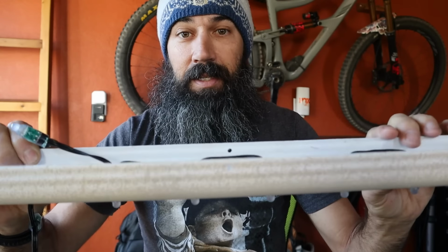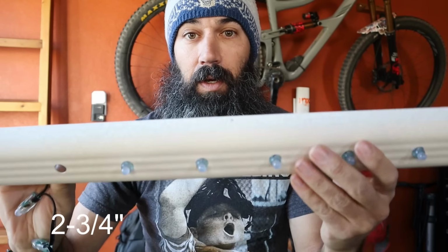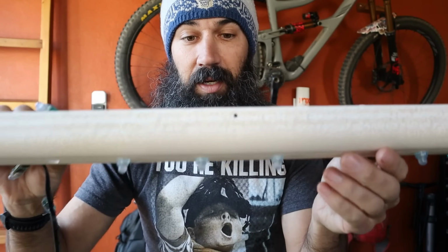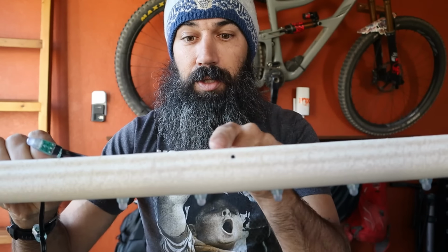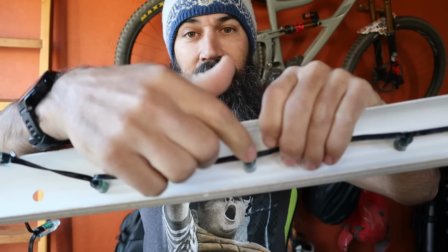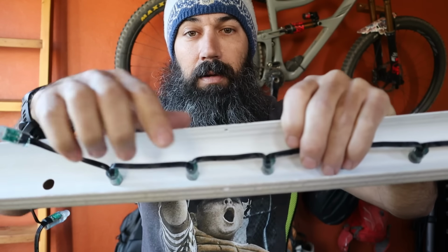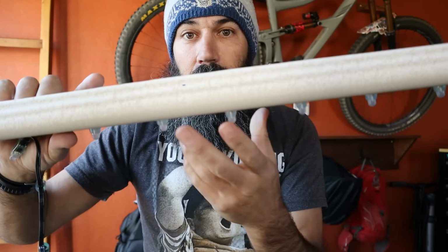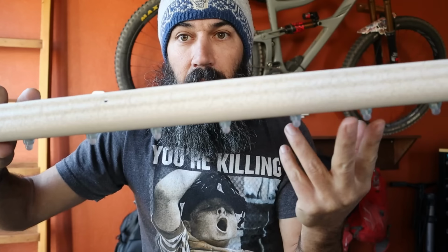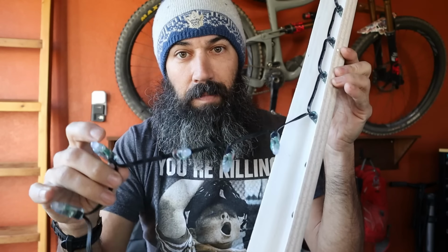Now the next thing you have to know is how far apart to space these for your string or strand of lights. I went with 2 3/4 inches on center. You could go a touch smaller than that, but I would not go any bigger than that. I would not do 3 inches. If you do, you're going to be really stretching these wires apart, and I think you're going to risk severing one of the electrical connections at where these pixels are. So if you do 2 3/4 between each hole, in one 10-foot length, I was able to get 43 pixels per.